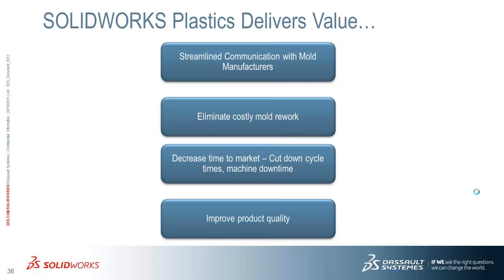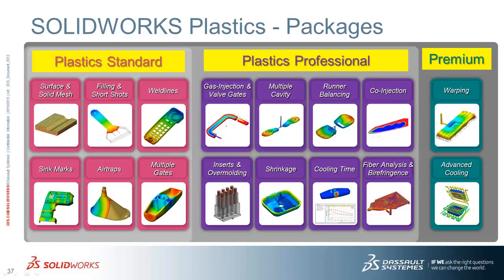With that said, let's go ahead and take a look at different packages offered under the SolidWorks Plastics portfolio. We've got Plastics Standard, which is associated with fill analysis, gives the user the ability to look up the fill times, knit lines, sink marks, air traps, and simulate multiple gates. The next level up is Plastics Professional, which has all the filling capabilities offered in Plastics Standard, plus the ability to model the packing scenario.